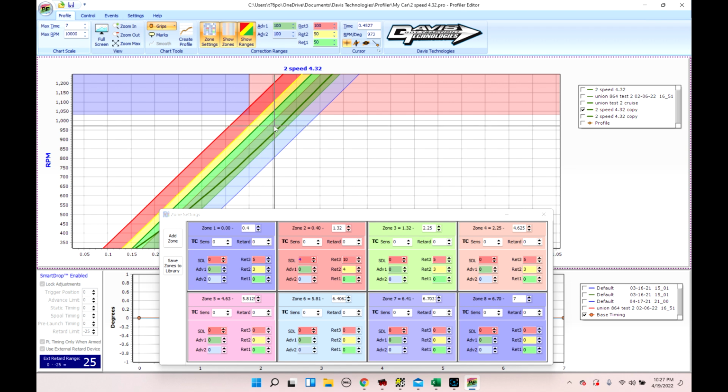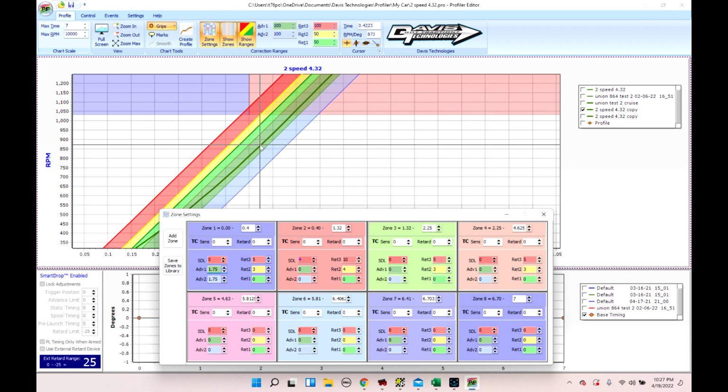So right now here, the tire and the drive shaft is behind, okay? The drive shaft's supposed to be up here, but it's down here. So we are in the advanced range, okay? I didn't have a timing advance in here, but I probably should have. So what you can do is it works just like the retard. You can add timing. Now notice, as I'm adding timing, it has to change your advanced stage or your advanced range 2 as well, because if it gets down here, we don't want to just stop advancing the timing because it's going to slow down even more, right?